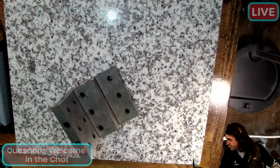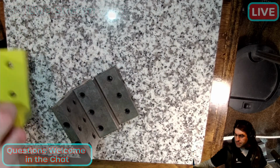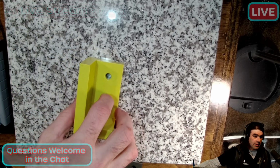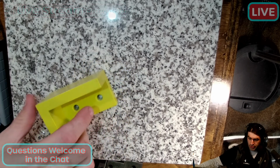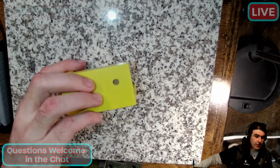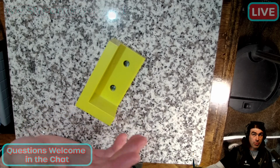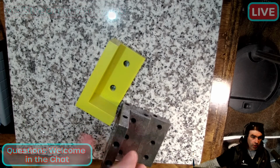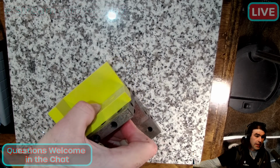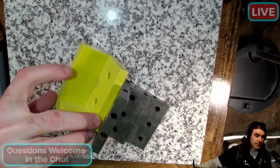I know it's not the same thing, but say we make this surface right here, this inside surface, datum A. It's doable, but it's not as sweet as if this surface was datum A. If that surface is datum A, we just put it on the plate and we're cooking, right? We could also just stick it right on our little block here and measure from the other side. It's pretty sweet too. It's not the end of the world because this is open, right?